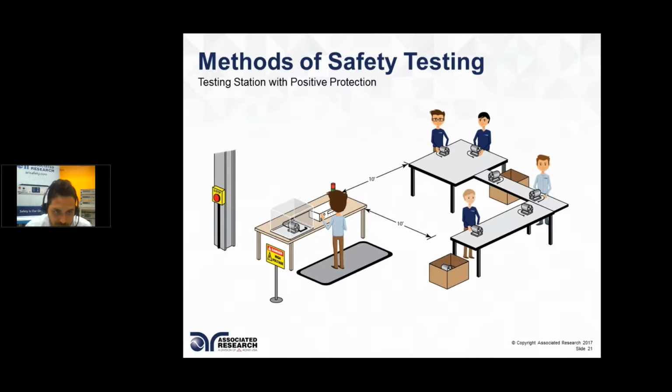And again, we see our e-stop, which is an emergency stop, right? If someone's getting shocked, someone can run over there and turn it off. If some sort of wire comes loose, you can hit that e-stop to mitigate that hazardous situation. And a high voltage sign lets visitors, or someone passing through on a tour, know this is a high voltage area. Just the fact that you're letting someone know that this is a dangerous area is also essential.